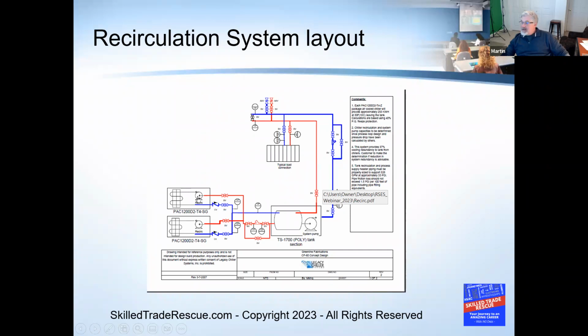So inside each chiller, we had a recirculatory pump. So these pumps here, their job in life was to suck the hot water off the tank, put it through the evaporator, and then back into the tank. That's what they do. And then we have a check valve in there that would prevent backflow if one pump was off and that kind of thing. All right, so that's the recirc side of the system.